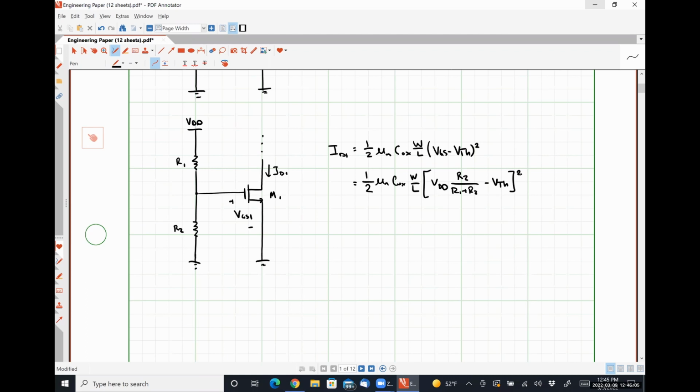What if all of those circuits suffered from temperature and power supply dependencies, okay? The temperature dependency, I guess you could arguably get away with if you stayed in one spot, in one room, where the temperature is going to be relatively constant, but your power supply value isn't, right? Because your cell phone is powered by a battery whose voltage depends on its state of charge.